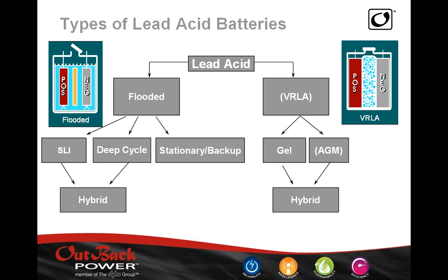You have the gel batteries, and you have the AGM batteries. Now, there are differences between the two, but essentially, this technology has evolved over the years, and they've improved their life, their capacity. Just to cite one difference here, for example, the average AGM battery has a float life of 12 years, whereas a deep cycle battery is not going to last more than 3 years on float.